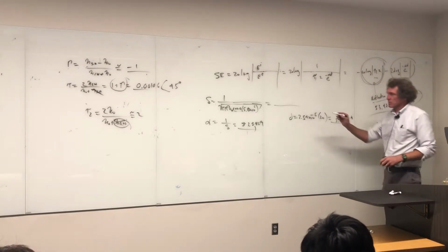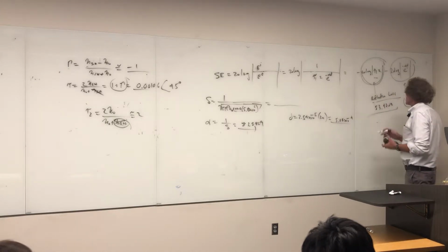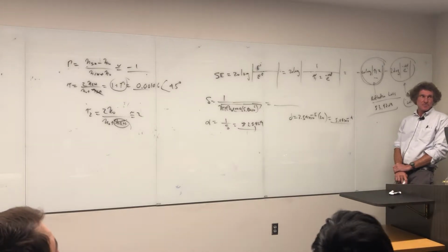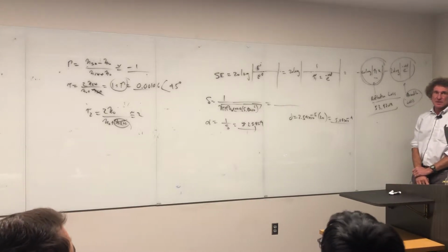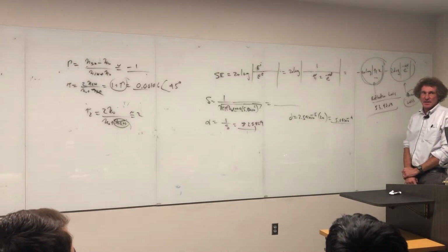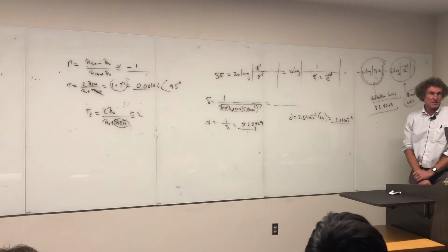Take that, multiply it by alpha, then stick it in here, take e to the minus alpha d. Sorry, it's a little messy. Y'all see what I'm doing, class? This is not hard to see. It's straightforward, but people will mess this up, especially on quizzes and tests. They will forget how easy it is to get alpha. Remember, this is a very good conductor.